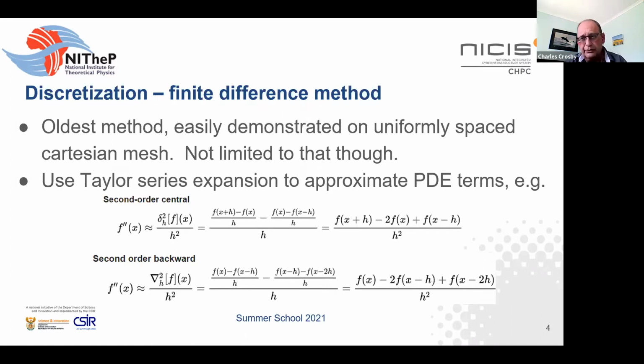The difference is important. You need the upwind schemes for convection dominated solutions to be stable. If you try and do this with central differencing, unless your grid's ludicrously fine, the method will be unstable, it will not converge. If you use first order upwind differencing, which is very simple, you end up with a method that's extremely stable and it smears more or less any kind of feature out of the solution. So you get a very diffuse solution.